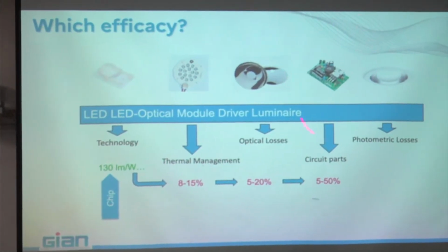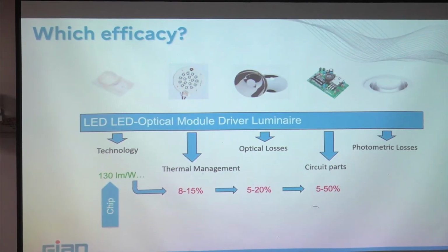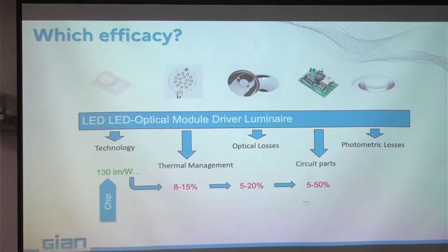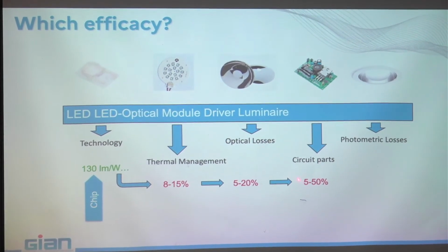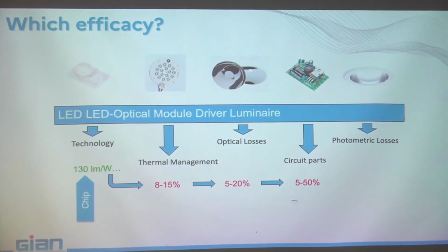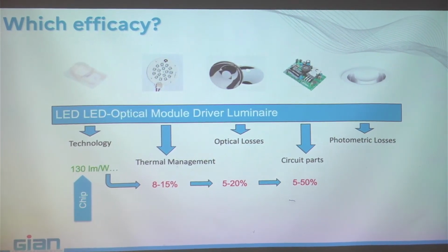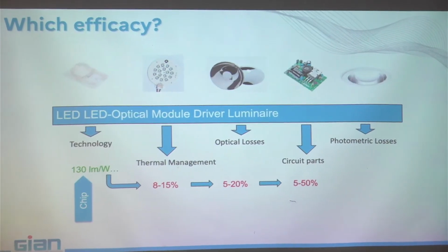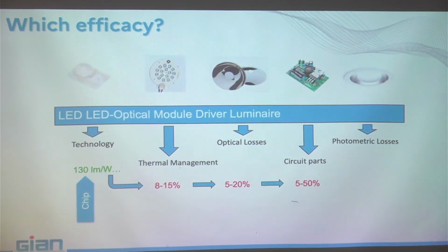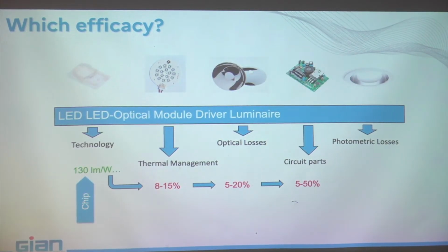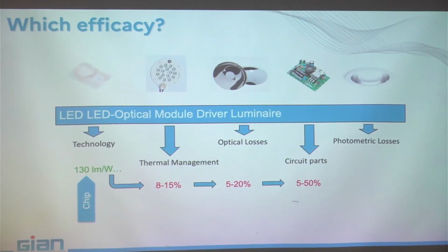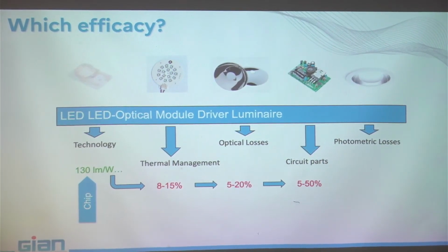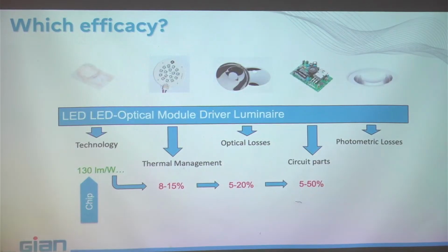Then you have to drive. And the driver, you are a specialist here, has losses. Excellent drivers, DC-DC converters, can go to a few percent. Good quality AC-DC converters, simple ones, can go up to 50%. Bad quality can go up to I don't know what. Forget it, or you double, you triple the power that you have to put in.